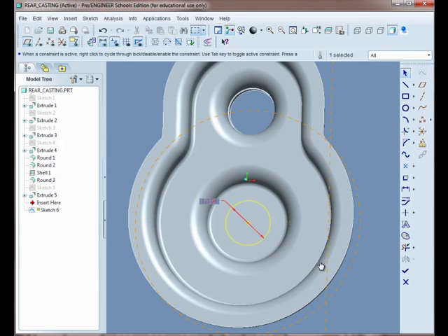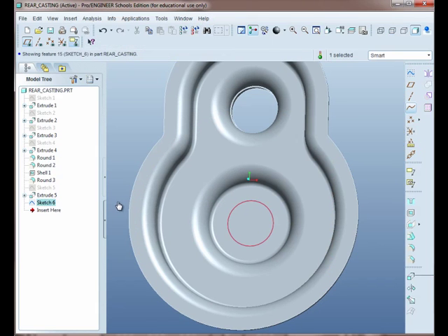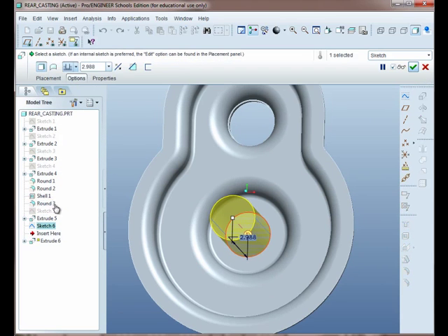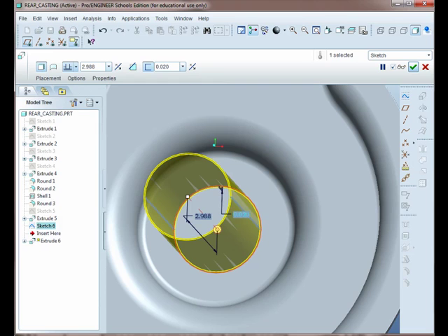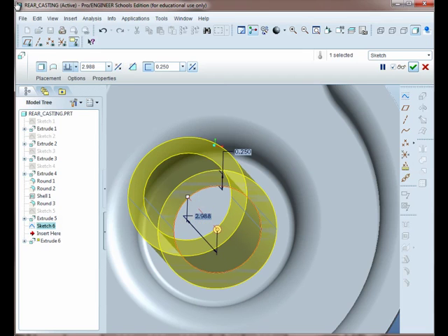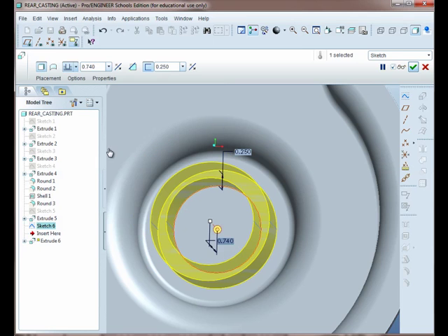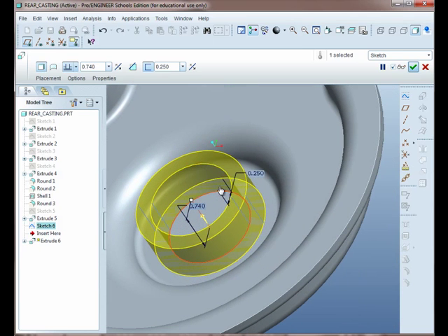So we could actually draw an offset circle if we want, or else we could do this. We could actually just go to Done, Extrude, and we have some options here. First of all, we could go ahead and hit this little button, which is Thicken Sketch. And now we know it needs to be 0.25 thick, so we select 0.25. We could flip it so the thickness is on the outside, and that's what we need. And this is 0.75 high for the extrusion. And hit Apply.